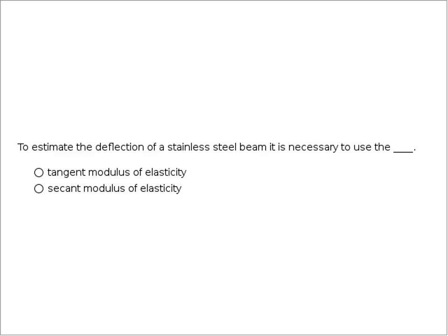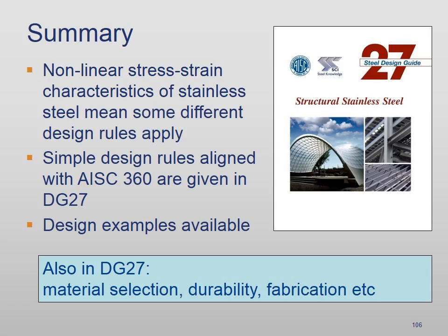Okay, so now let's bring us back to the concluding slide, and let's go through some of the questions that we have received. So, Nancy, since Fy is a critical factor in most design formulas, if you have material that is dual certified, for example 304/304L, do you have to use the lower yield strength, and isn't that a very large penalty?